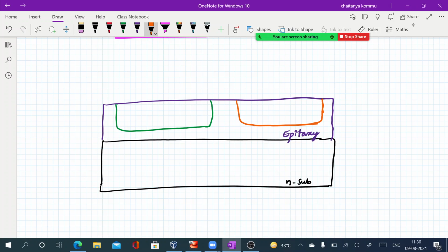Now the mask is defined for both N well and P well. Only one mask is sufficient for that. Therefore no additional steps are required. Whenever we are digging the N well, we create a pattern on the same plate for the P well also. That's it.